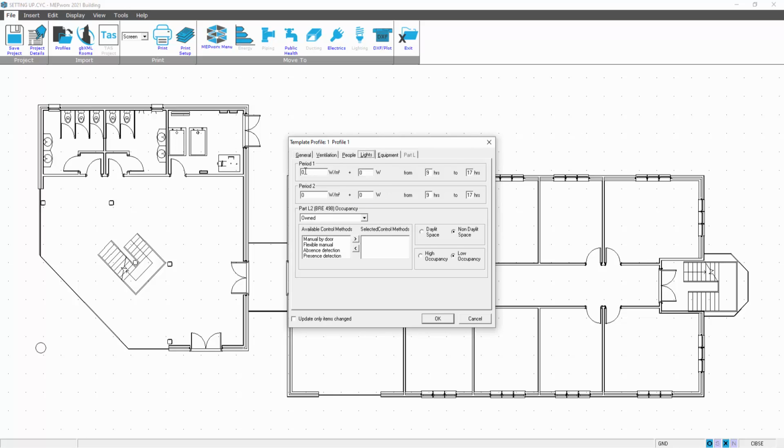Lighting can be put in, so we could say okay, 8 watts per meter squared, so you've got LEDs or something. Later on, if the lighting people get involved in the design and you come back to the building and energy program, it will flag that and it will ask you whether you wish to update, and this second column will then be populated by the actual gains from the manufacturer selected fittings, and this initial column will be reset to 0. That's a choice you make. The program will prompt you for that choice. You decide what you want to do.